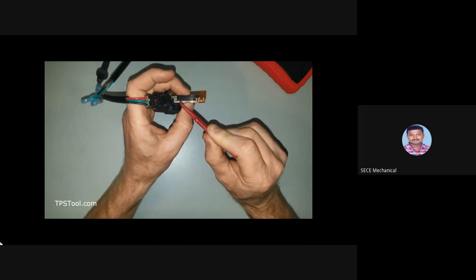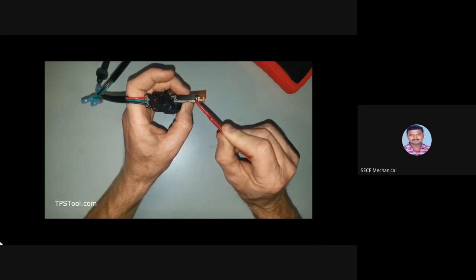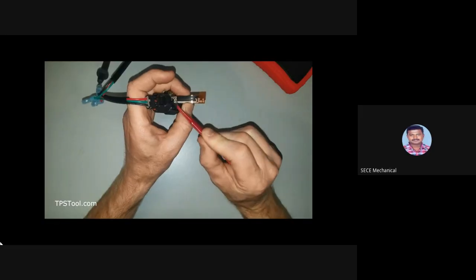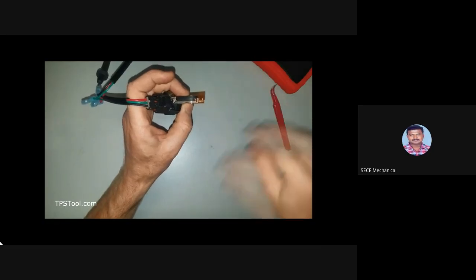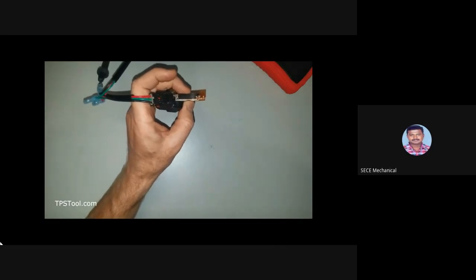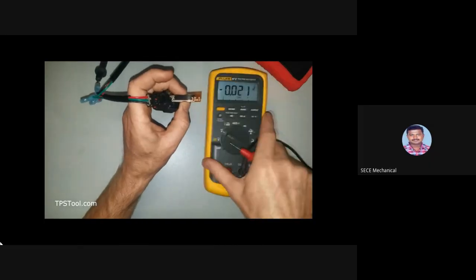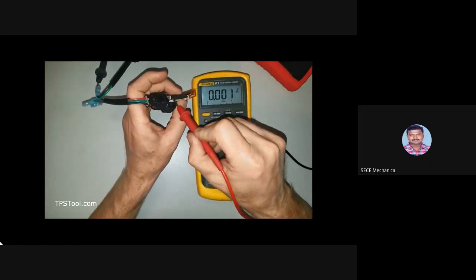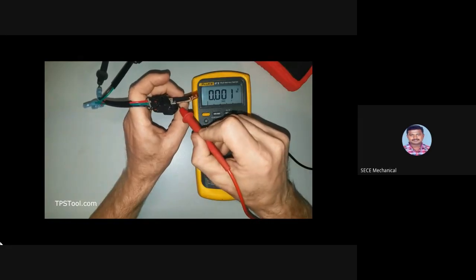And as the current runs through the conductor, it loses voltage all the way across. So on this side, it's going to start at 5 volts. On this side, it's going to have essentially no volts. And it's going to lose all the way across. So let's take a look. I've got my meters connected since this one has a probe. So it'll be easier to use for this example. So watch, as I touch over here, I had them backwards. This is the 0 over here.